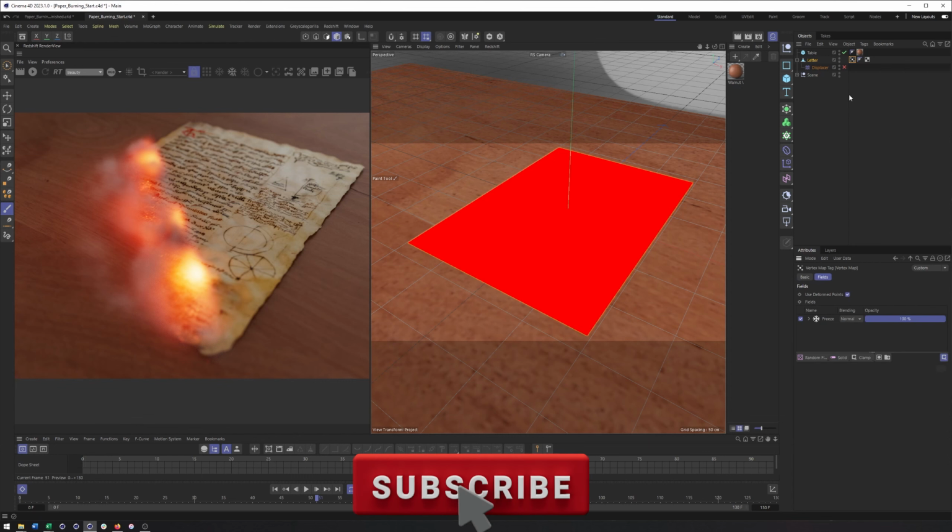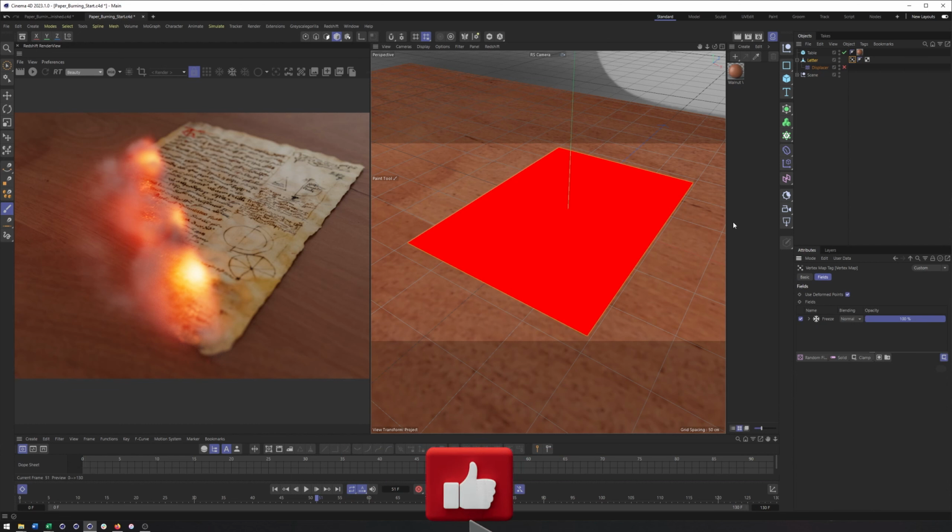And so we are going to use fields here to really control our vertex map, which we will then use to control pretty much everything we're doing inside of Pyro, where we want it to burn, which is going to be right here. We'll also use a vertex map to blend between the different materials, get rid of the opacity of the letter, fade it off. So a lot of the heavy lifting here is being done with these vertex maps.